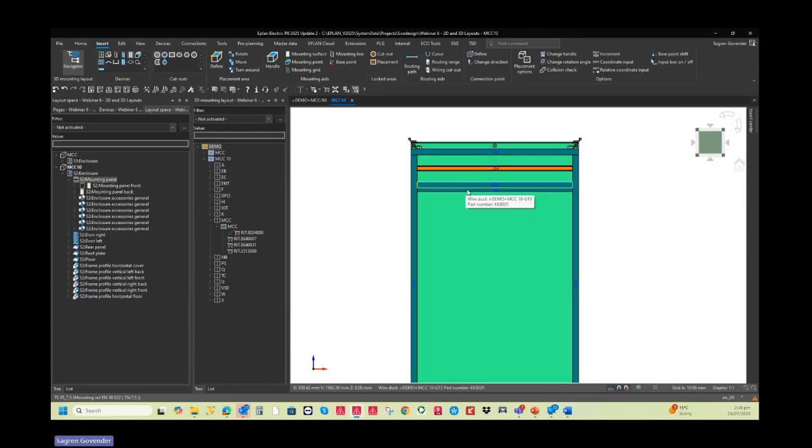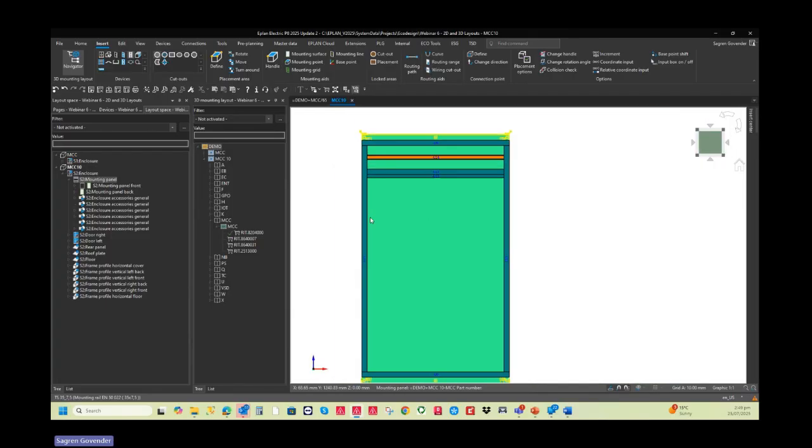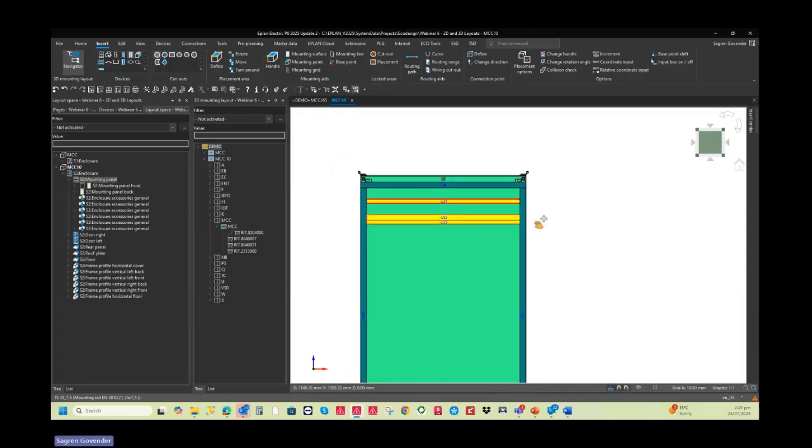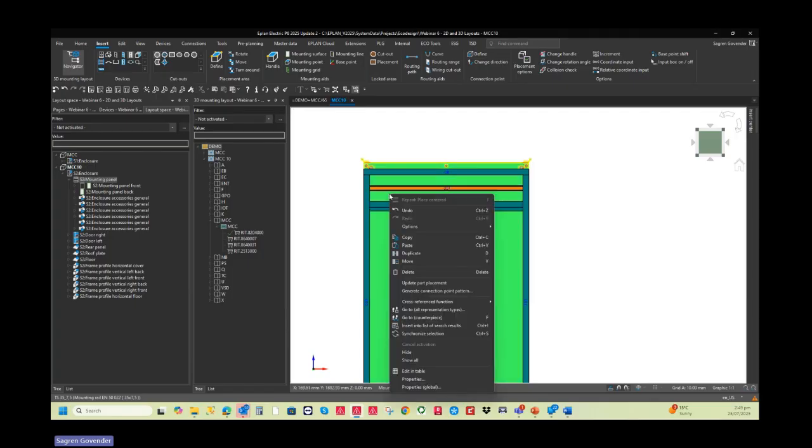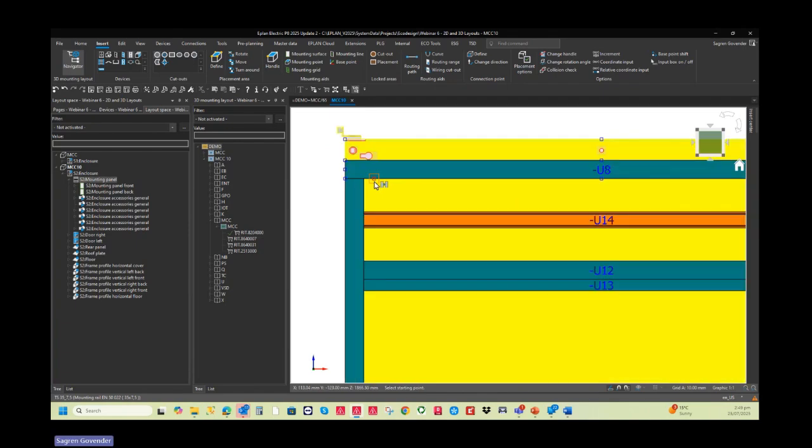Okay, back to my front view. And now I want this 5 times, and I can use a trick for that. Select these DIN rail, trunking and so forth, and right click, go duplicate. The shortcut for that is D. Pick this point here.